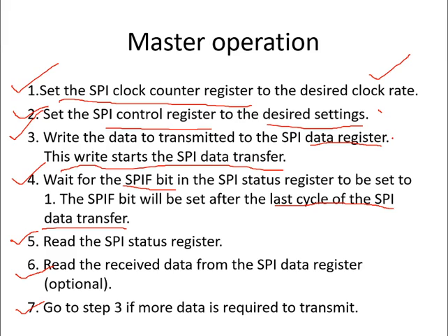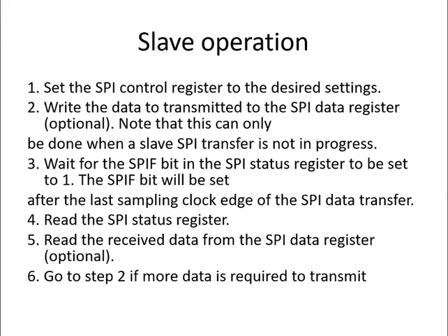It is similar to your UART working. In case of UART also you are doing the same thing, but the only difference here is that it will also initiate the clock signal to communicate with the slave. So this is about the master operation of the SPI module present in the LPC2148. Okay. Then we will go for the slave operation.